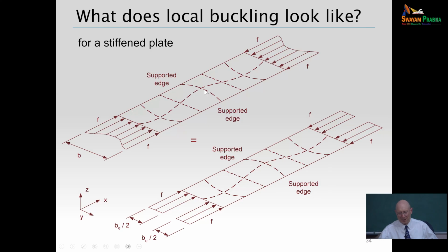However, out in the middle of the plate, where we're in the middle of the local buckling, we're tending to be more flexible in terms of longitudinal compression. So therefore, we tend to develop less stress out in the middle of the plate. Well, it'd be rather complicated in design to work with a stress distribution that's some smooth function to represent this. So what do we do? We basically say, okay, we're going to discount the effectiveness of the plate out in the middle. So we've got a total effective width that has two halves here.